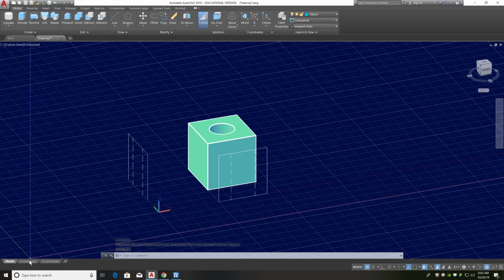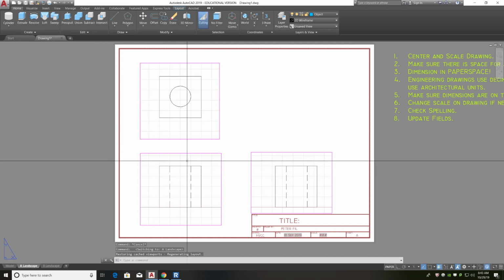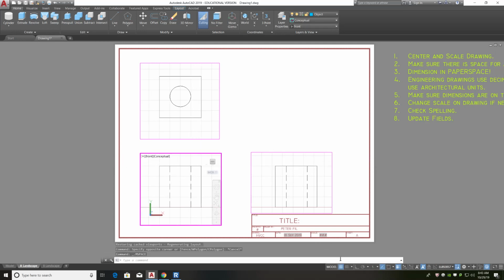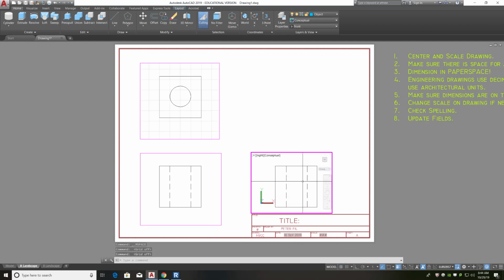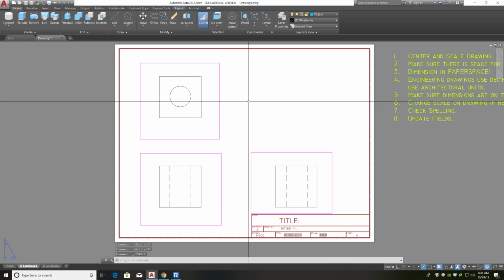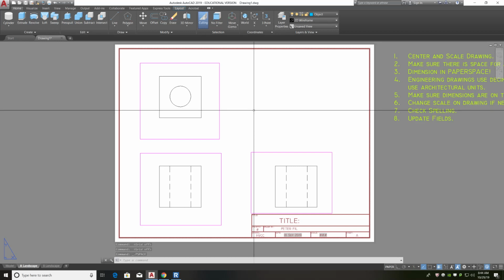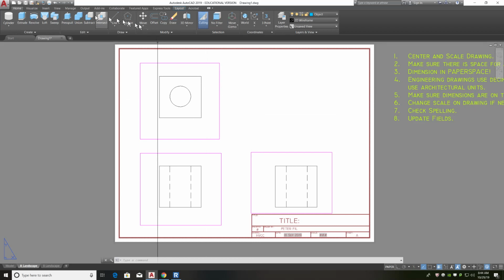Okay, so your job at this point is you can go in here, double click, remove the grid just like in any other drawing. Kind of clean it up if you like. And then you can add your center lines, add your dimensions, and do what you need to there. Notice, however, that up in the ribbon there is no dimensions. Okay? Because typically solid modeling is used to just model, all right, and not really to dimension.